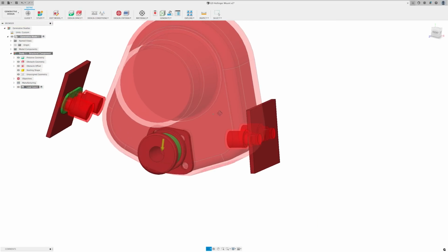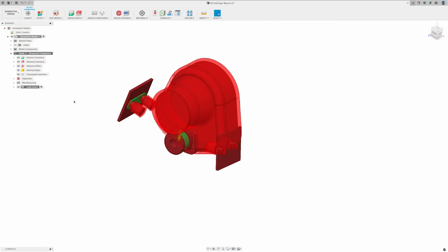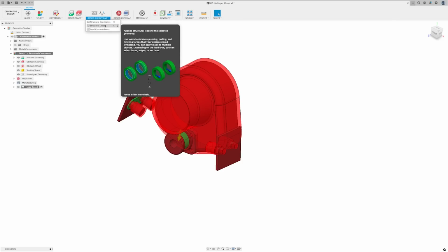After this, we can add our structural load, which is the key part of this process that needs a bit of extra thought. This gearbox weighs about 35 kgs, but it's also connected to the engine, which is supported by the mounts, as well as the drive shaft and various other fittings. So it's quite tricky to put an actual figure on how much weight is supported by this mount. On top of this, the car pulls between 1.5 and 2 Gs when cornering and braking, and the mount is subject to significant amounts of heat and vibration.